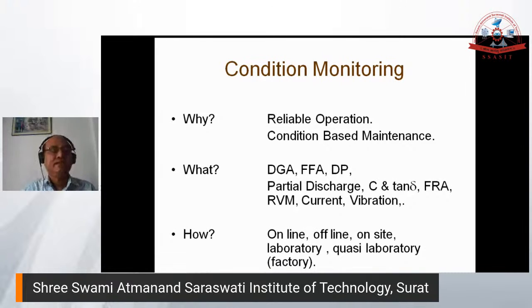There are different techniques specifically for the transformer: dissolved gas analysis, furfural analysis, degree of polymerization, partial discharge, capacitance and tan delta, frequency response analysis, recovery voltage measurement, current measurement, vibration measurement. All these are done for the condition monitoring of this equipment.